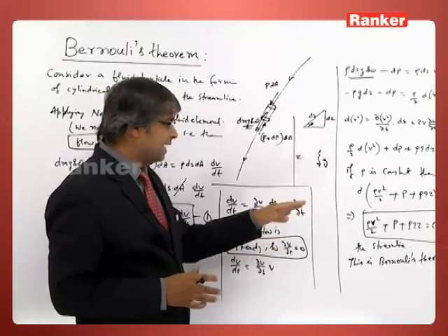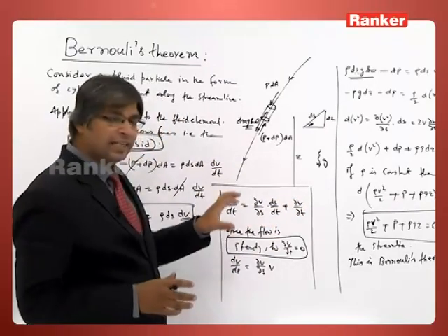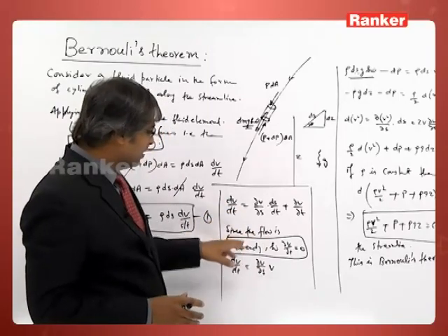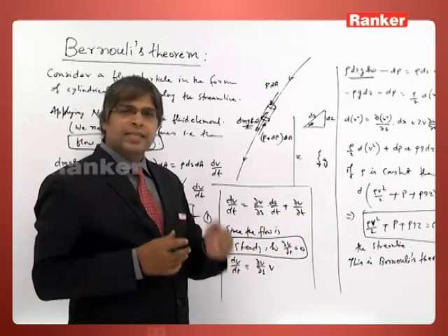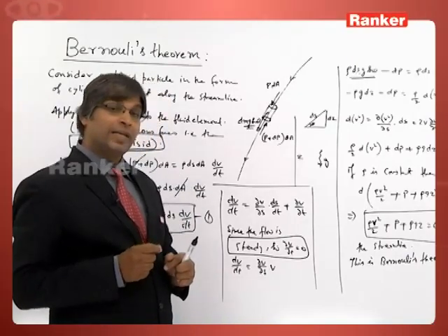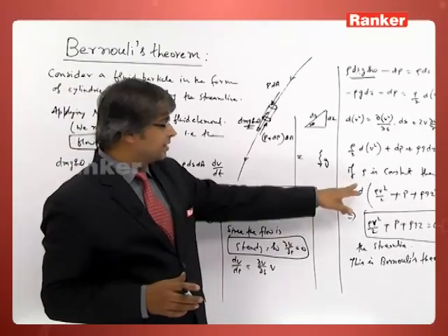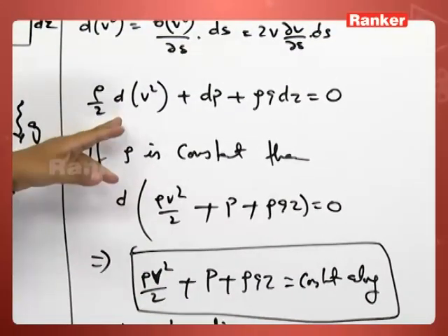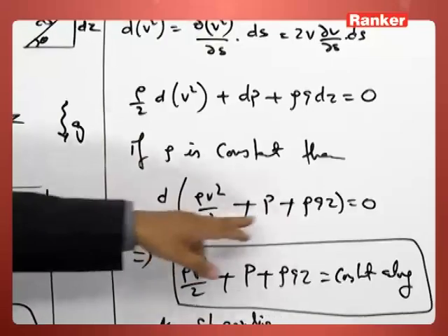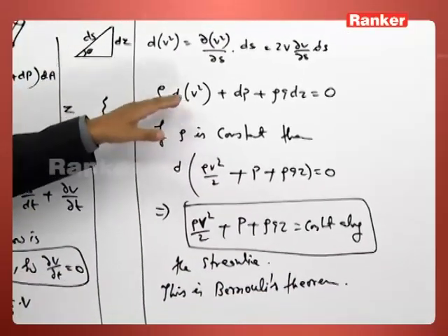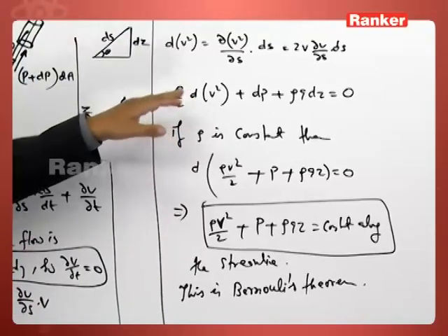So we have seen that all these limiting conditions we are imposing on the fluid particle come from where? Now suppose I require my flow to be compressible. That means I have to work from this earlier part, not from here, because here I have assumed rho constant, and only then is this constant. So in that case we will use from here. Some modifications will be required.